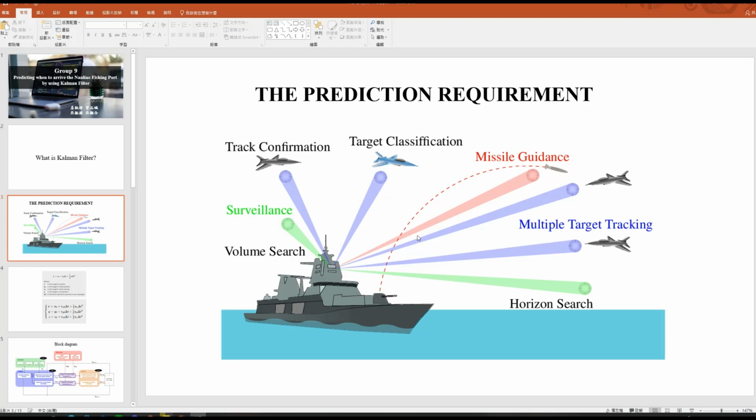The tracking radar sends a pencil beam in the direction of the target. Assume a track cycle of 5 seconds. In other words, every 5 seconds the radar revisits the target by sending a dedicated track beam in the direction of the target. After sending the beam, the radar estimates the current target position and velocity. Also, the radar estimates or predicts the target position at the next track beam.